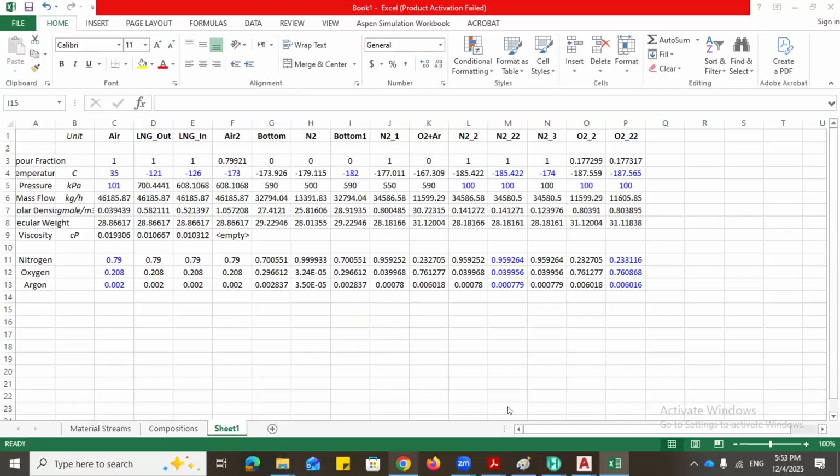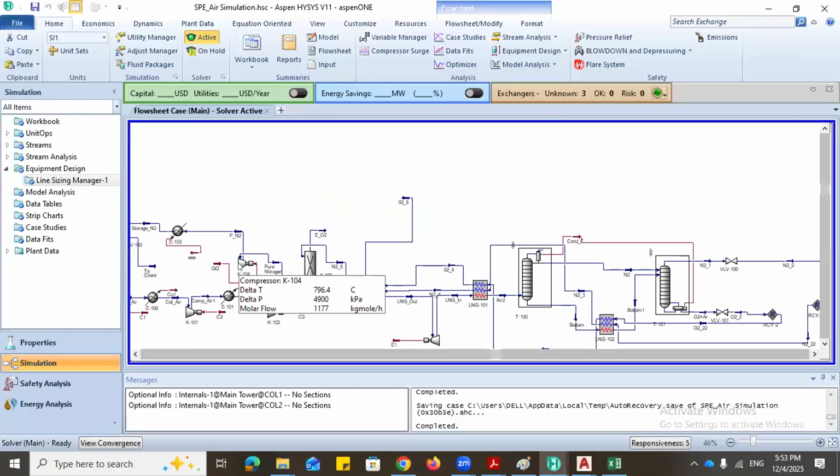Now let's go. A lot of things. These are compressors, coolers, energy heat exchangers. We have our control valve. We also have a standard for sizing our control valve, what we call Cv. All we are looking for is Cv, right? And this control valve you are seeing here, we also have gate valves and bypass valves. Maybe you want to design this valve as fail to close or fail to open. I'm not taking you into the detailed design, right?